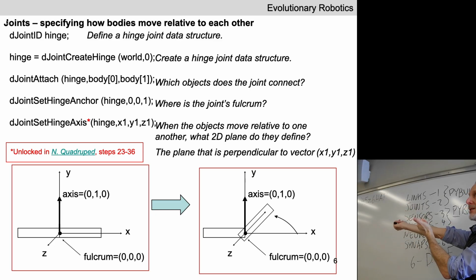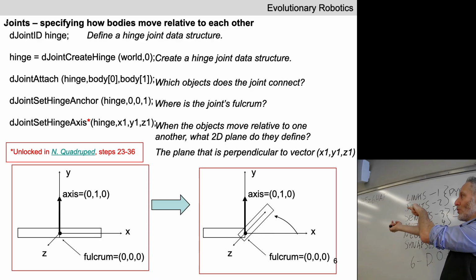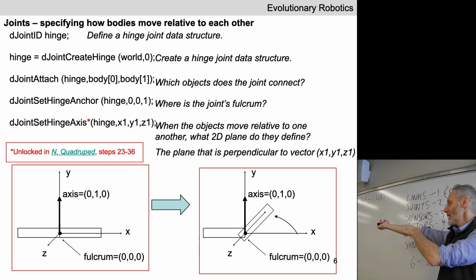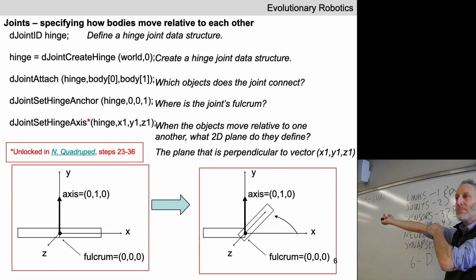Let's see, did I get that right? Yeah, this is the, oh no, sorry. We'll do X along here. Let's just think about the X position of my lower arm and my upper arm. If this tries to move this way, so does this one. They cannot independently change their X coordinate, luckily for me. I'd be in a lot of trouble if that weren't the case. So the elbow joint has removed at least 1 degree of freedom. Has it removed any others?